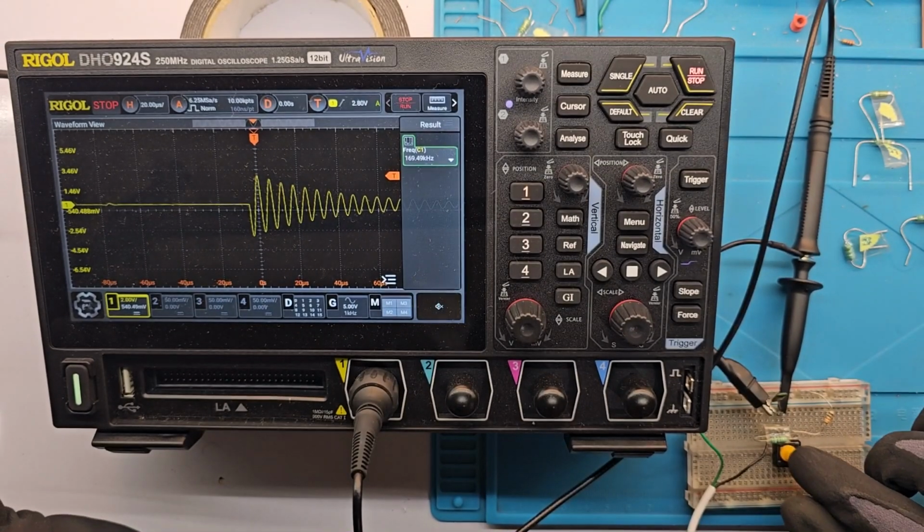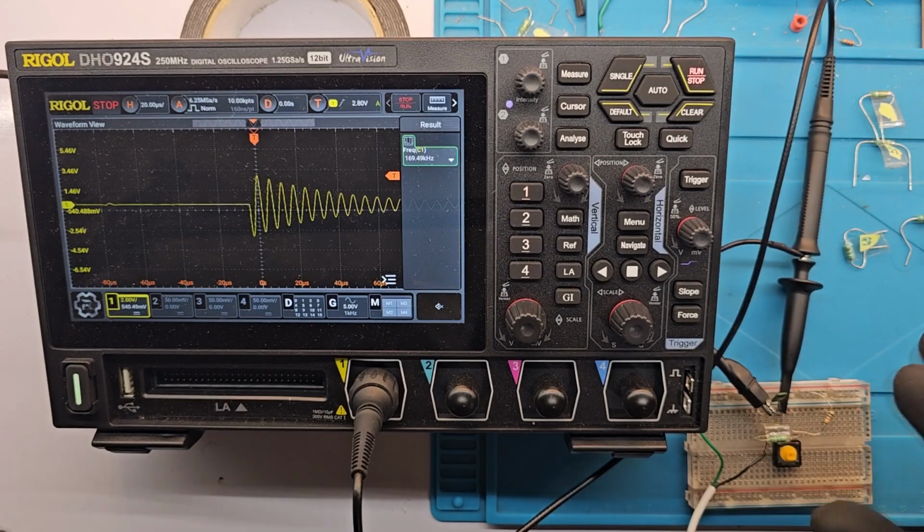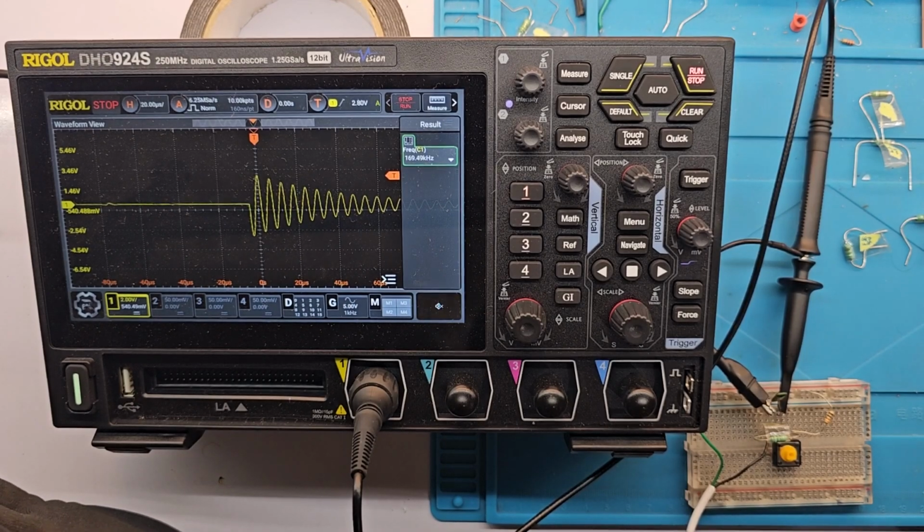So this is the basic idea. You need to put a pulse through this LC tank circuit and just capture the resonant signal there, and this is how you find out the inductance using a pulse and an oscilloscope. There's no need for any Arduino or function generator or anything. This is the simplest way to do it.